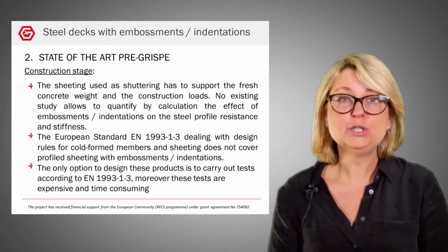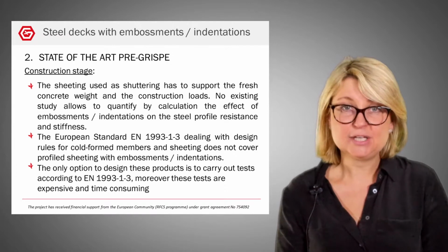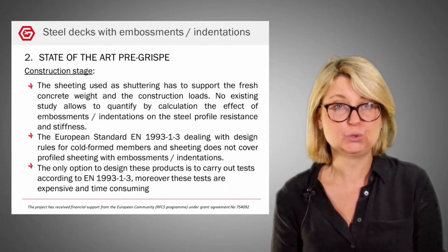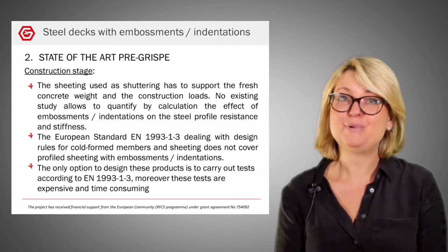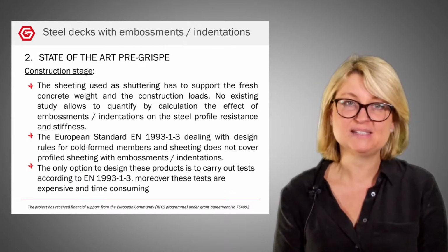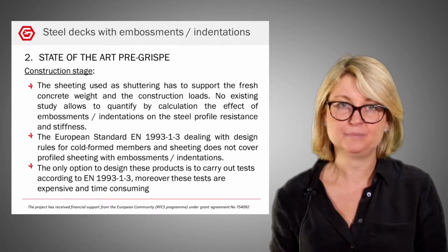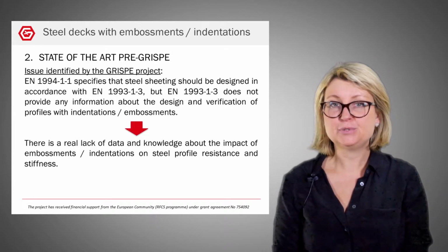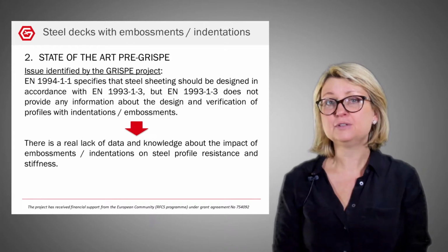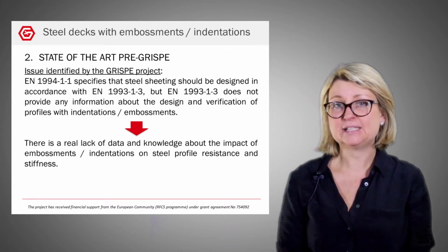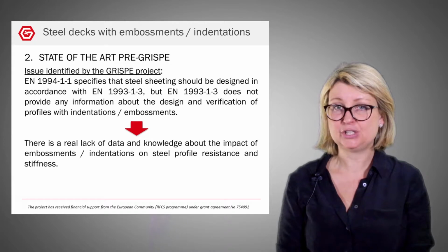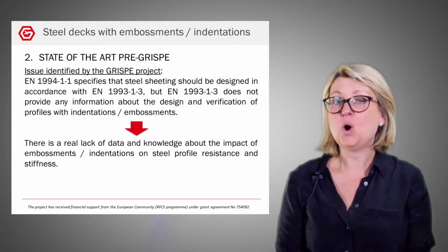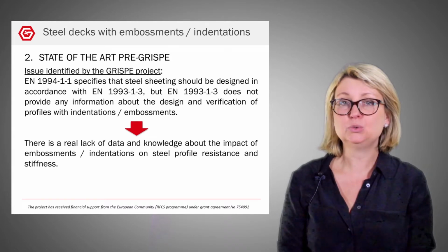Therefore, the only way to design such profiles is to perform testing according to Eurocode 3 Part 1-3, but these tests are expensive and time-consuming. Thus, at the beginning of the GRISP project, we could observe that despite the frequent use of steel decks with embossments and indentation, no information is given by Eurocodes or by literature on how to design them.